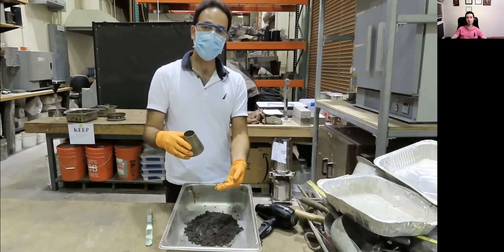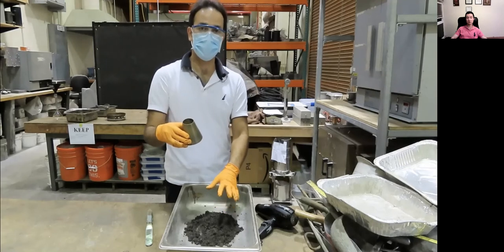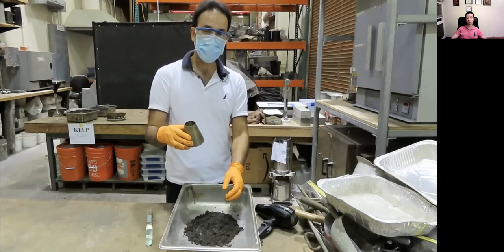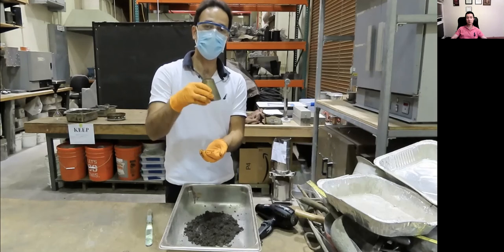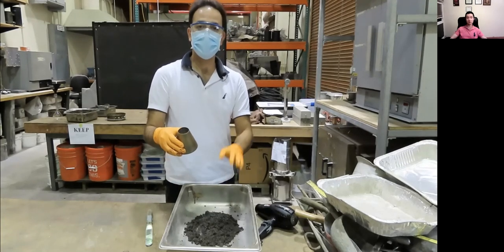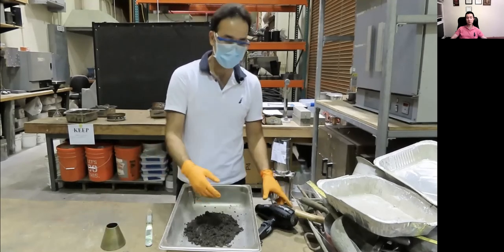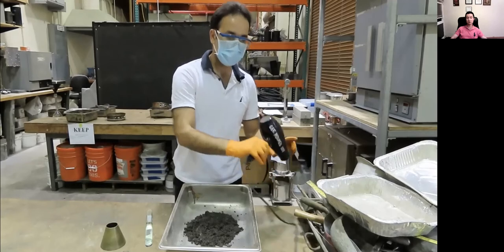If the fine aggregate has the form of the mold, it means that it is wet yet. And if it is dry, and if I take up the cone and it collapses, it means that the aggregate is in SSD condition. For now, just dry the aggregate and then get back to you guys.